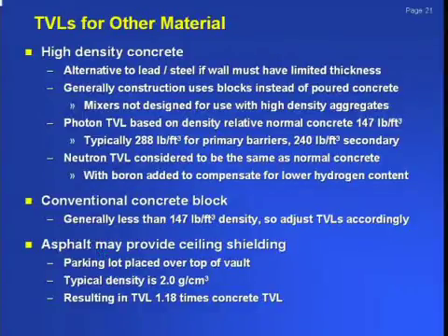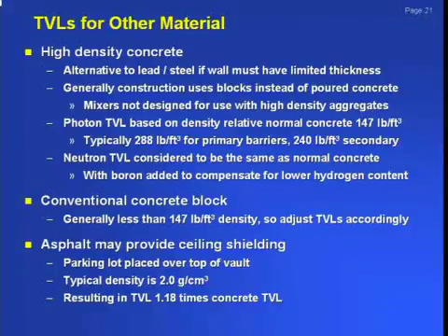But TVLs for other materials, like high density concrete, vary, as there are multiple densities of, quote, high density concrete available. If you go to the floor down there in the exhibit hall and talk to the different vendors, you will be amazed how many different densities you can basically get from the different concrete block suppliers, or you can have them mix it and pour it to your specification. If you have a contractor mixing on site and pouring their concrete, make sure you get samples. Have your contractor do a sample from the pour they're actually using and verify that it meets your specified minimum density.